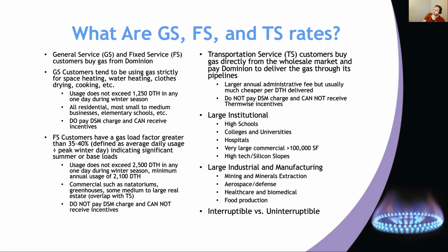Do you know, in your experience, would you rather use the flow rate from the people they're buying from or the flow rate from the Dominion meter? I would recommend using the flow rate from the Dominion meter because that is the meter at the entry point between the pipeline and the customer. That meter is going to be the most accurate.